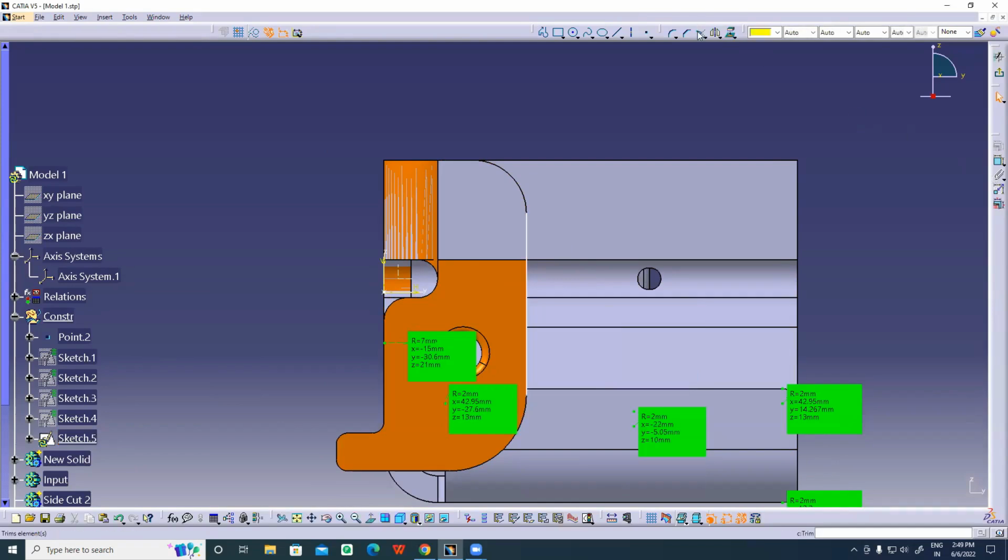Okay, and I'll go to the trim tool. I'll be extending the length of this, and I'll be extending the length of this on this side also. I'll go to dimension, selecting the line, selecting the vertical axis, and I wanted to apply a dimension to the end point of these lines also. I'll be applying a dimension to this and selecting a line.